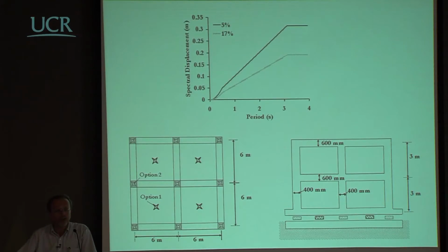Or you may say, well, why should I use 9 isolation devices? I could use 4. But if you use 4, then you need a slab here capable of taking the loads coming down here and putting them here. And then you need to have the lower slab here that will be able to take these loads and to put them on the ground. So there are kind of problems. Talking about L'Aquila, I will show you many isolator devices. But anyway, this is something that you may keep in mind.